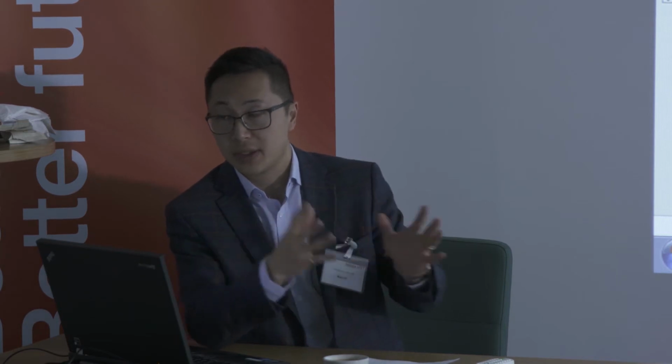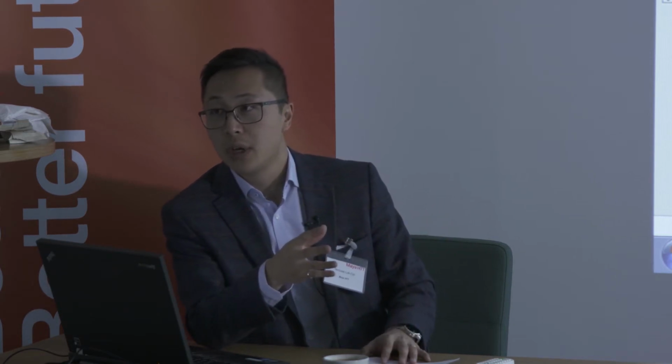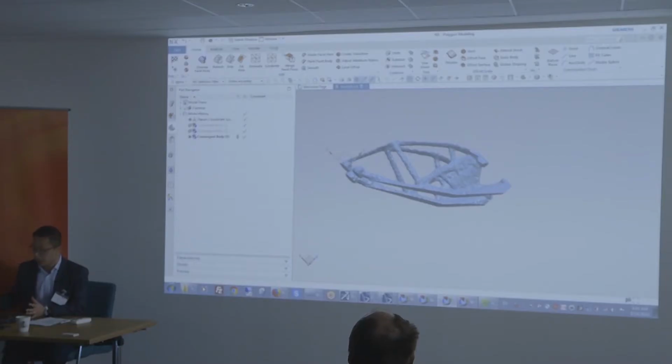Can you import SolidWorks files into NX? Yes. You won't get the history tree, because that's only in the specific software. However, they will come in natively without having to go through a translation process, so you won't lose any of the features. From there you can use our convergent modeling capabilities or our synchronous technology capabilities to make those changes dynamically. I'll show some of that later on.